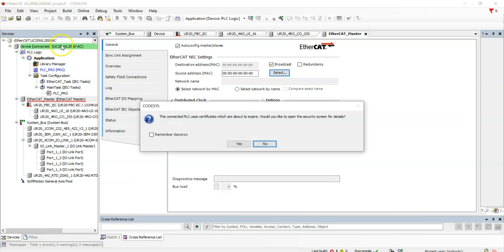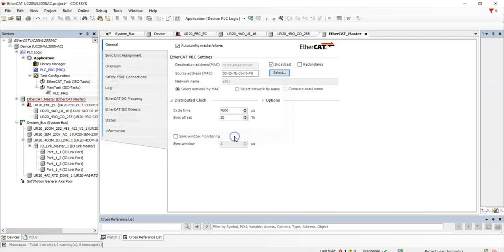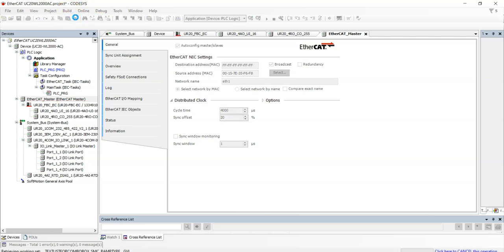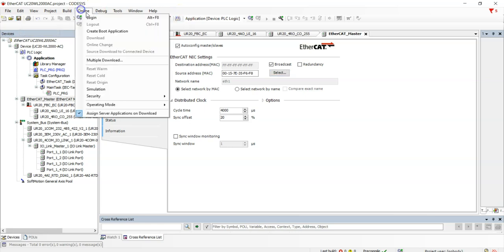There, you see there, we've gone devices connected. I'm not too concerned about certificates. Again, I'm going to ignore that for now and bind to the Ethernet port of the controller. So I want to connect to Ethernet 1, which is actually port 2, and it's populated with the MAC address, so that should be okay now. So if I build again, it should build hopefully without any errors. Yep, no errors, no warnings. I'll do a save at this point. Keep saving your work.